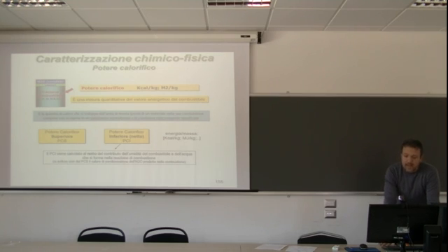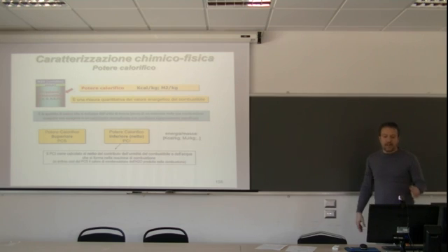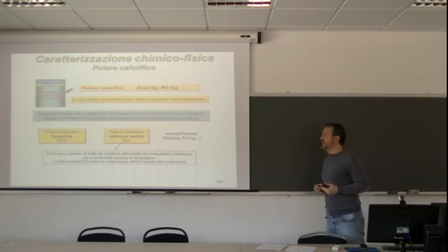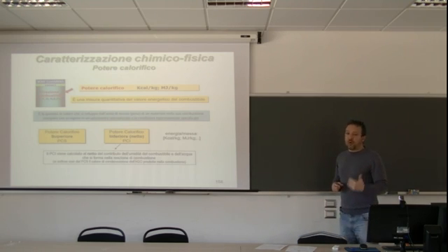Heating value, and of course we have to make a difference between low and high heating value, and it depends on the water that you have in the biomass, because water is not only an element that substitutes the burning part, but if you have a thermochemical process, water at combustion temperatures, so of course more than 100 degrees, has a phase change and takes some energy away from the system, which is the energy to pass from liquid to gas.